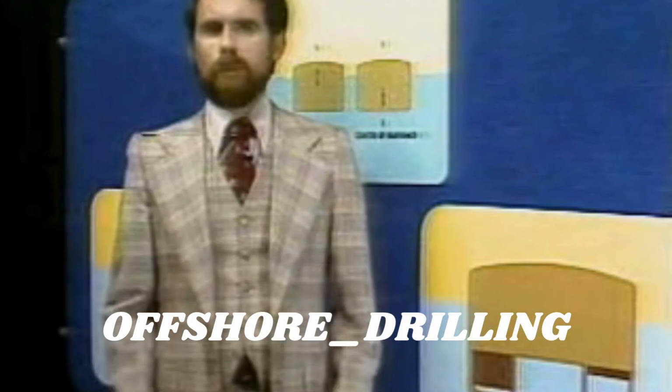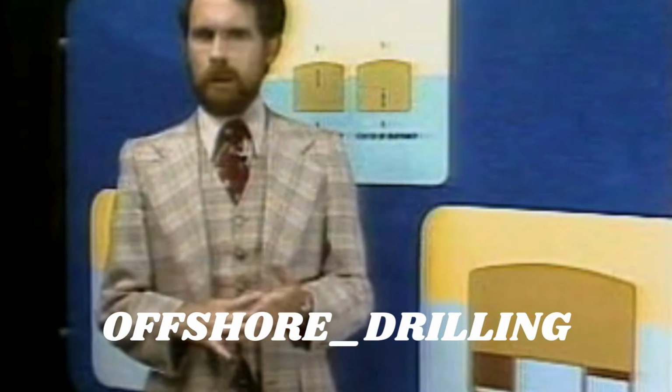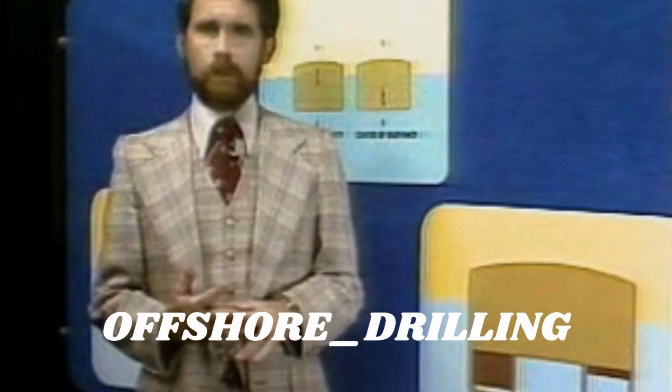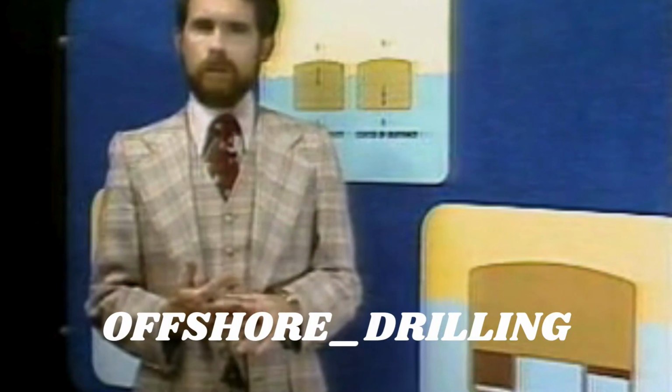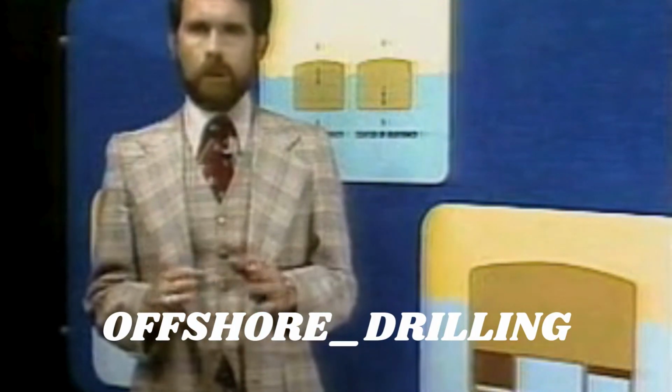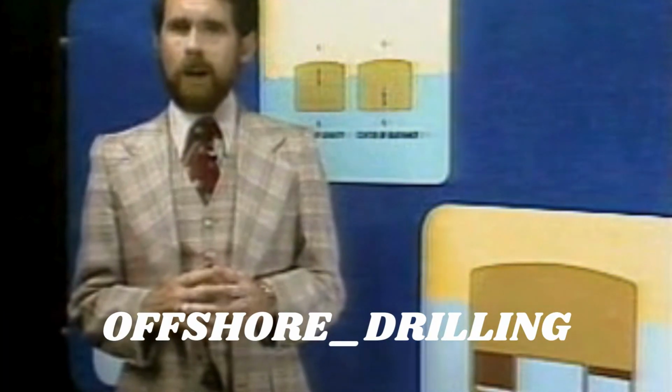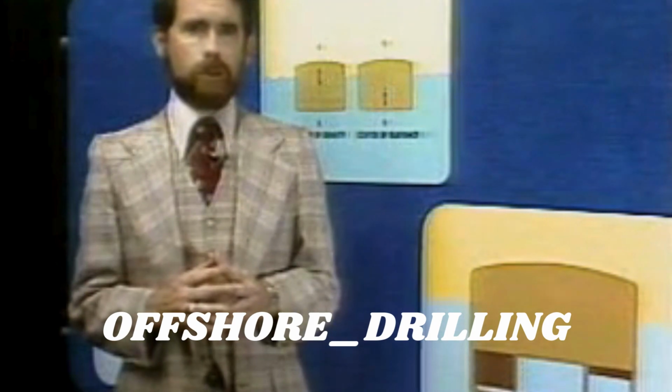The maximum free surface figure is tabulated for each tank on the vessel by the naval architects when the vessel is being designed. It is important to remember that the free surface correction for all slack tanks must be included in the calculation of KG for initial stability.